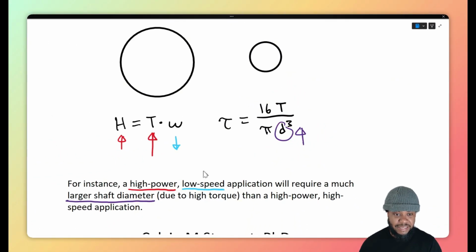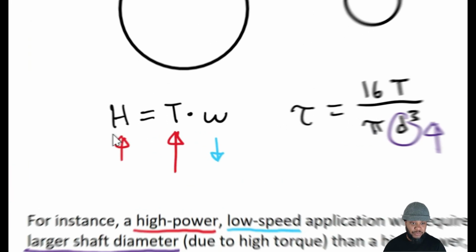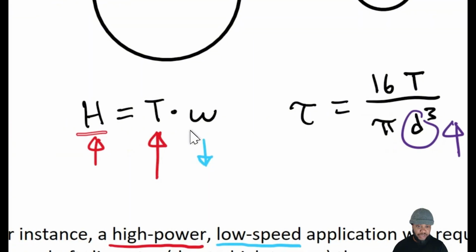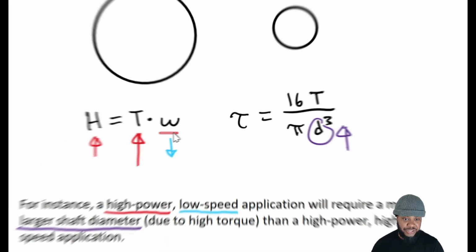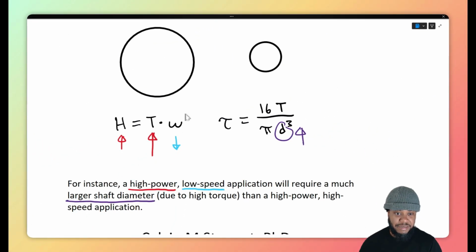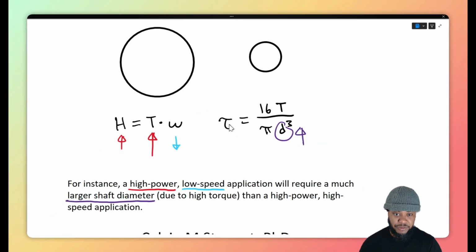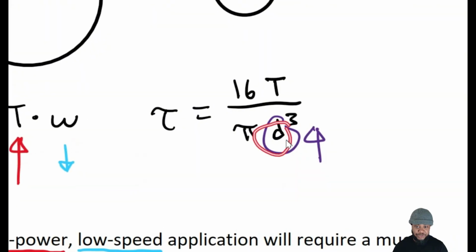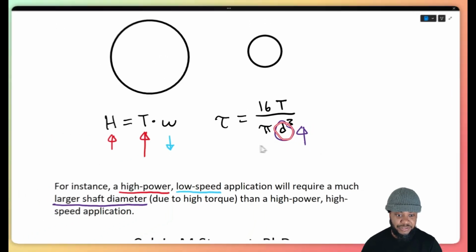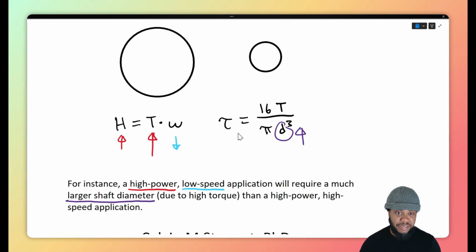So this highlights that in order to size the shaft properly, we have to consider what power we're transmitting, what speed we expect the shaft to spin up to, and then size accordingly to the material limit of stress and the dimensional, and then end up with the dimension of our shaft's design. And with that said, we've got the basics of the relationship between power, torque, and speed.